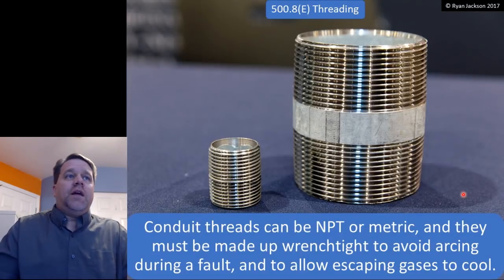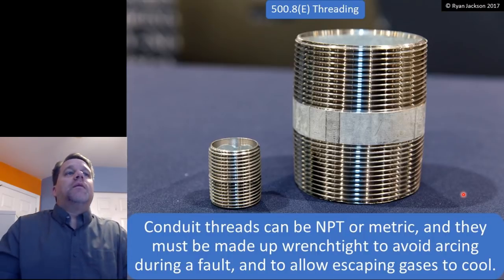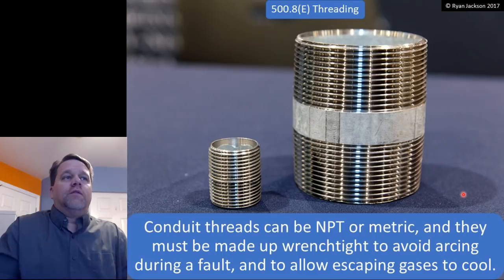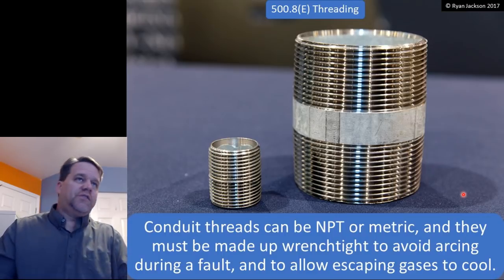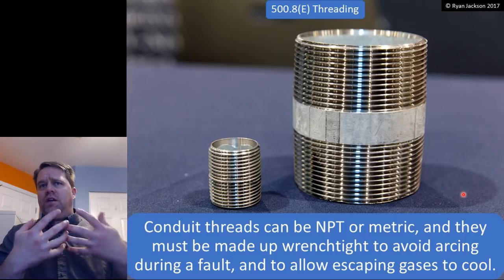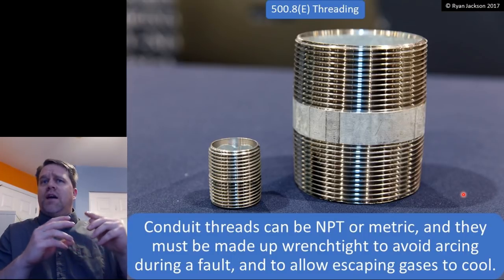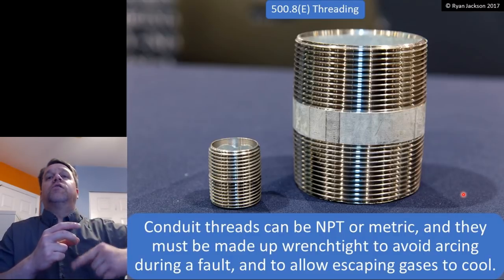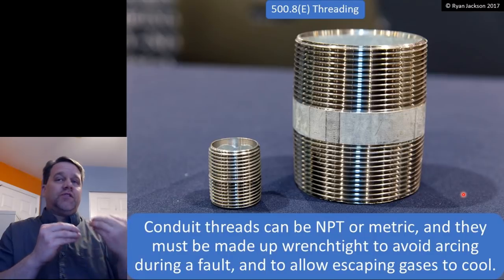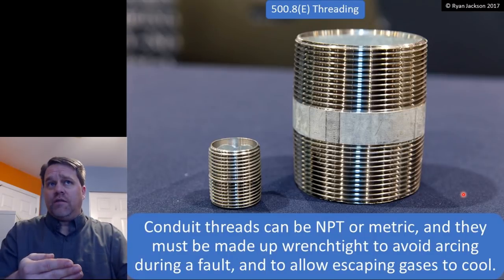500.8(E) talks about threading. Conduit threads can be either NPT or metric, and they must be made up wrench tight to avoid arcing during a fault and to allow the escaping gases to cool. So again, we have an explosion inside of the conduit system. Those hot burning gases have to swirl through the conduit threads, fight their way out, and cool themselves off to a temperature that's lower than the auto ignition temperature of the surrounding environment.